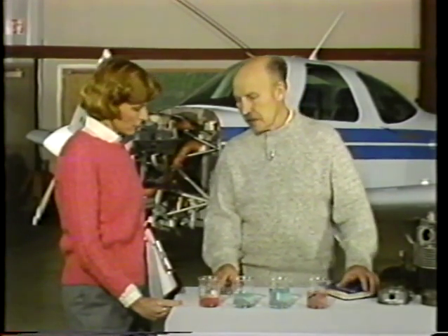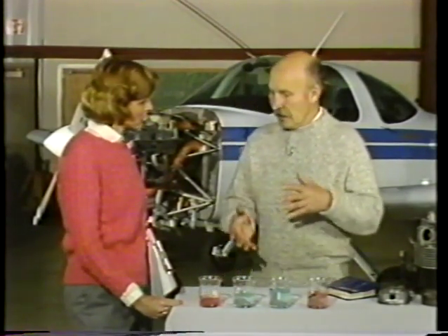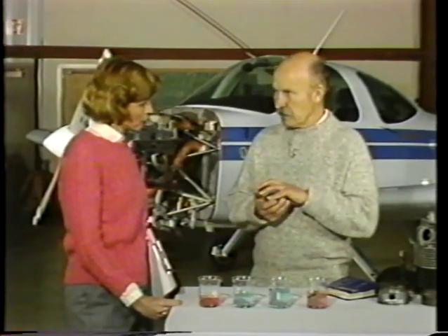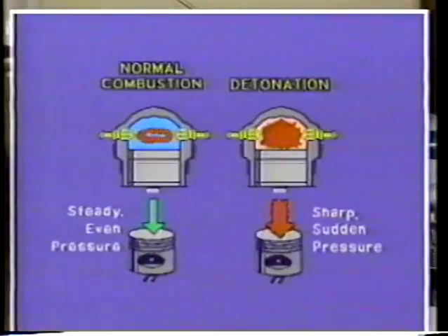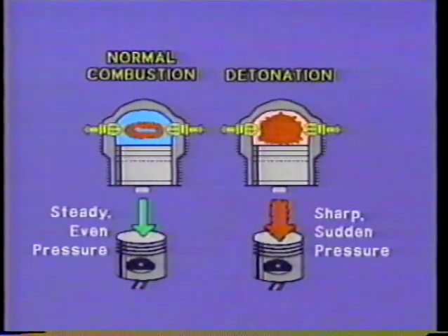Now, detonation is a characteristic, as I said, of the fuel as it performs in the combustion chamber. Normally what happens in the combustion chamber is that the fuel-air mixture is ignited and it burns slowly across the fuel-air mixture. And this provides an even pressure on the piston to push the piston down and give us a good uniform pressure in there. Detonation occurs when normal burning starts, and then the fuel-air mixture explodes, and this gives us a very sudden shock to the engine.